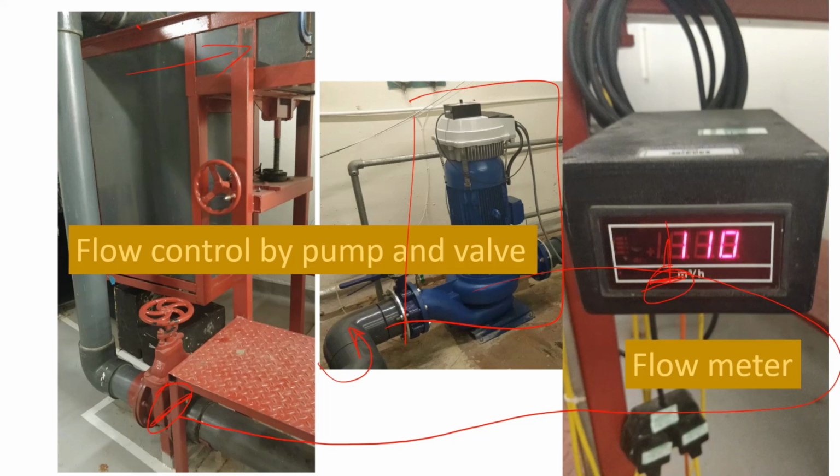There's a flow meter on the system. It's actually electromagnetic, and it counts the flow, and there's a reading on it which we have to take note of. This isn't the reading from the lab, so you take note of the data in the Excel sheet, but do note that the units are in meters cubed per hour, and we always want units of flow in meters cubed per second, so you do need to adjust that.